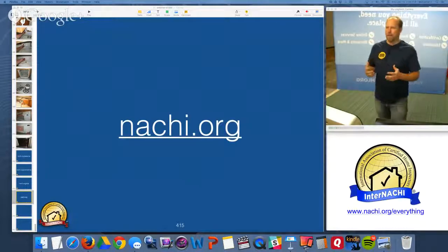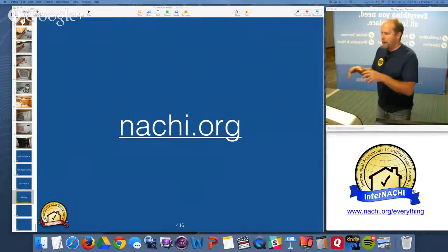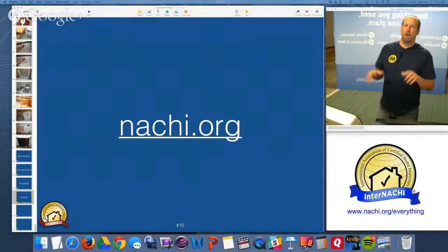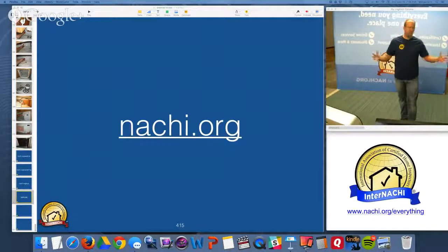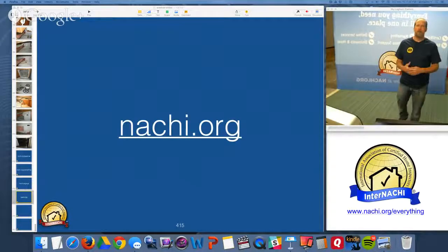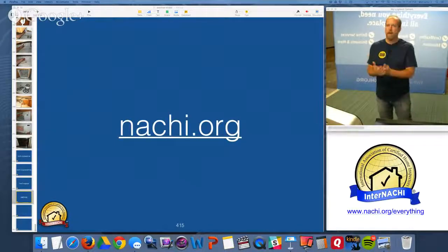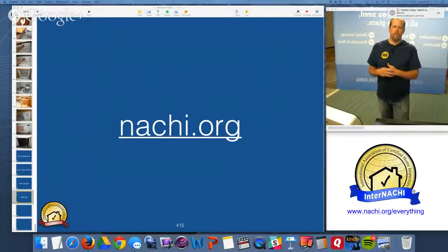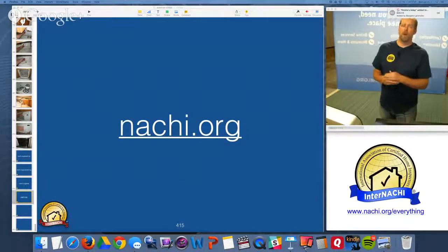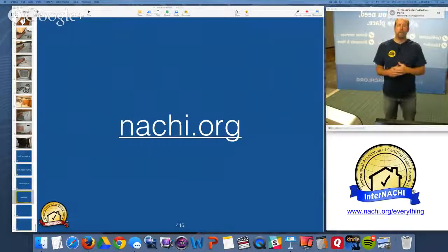So S-traps is like one of the easy things that new inspectors see and point out and call it a defect. Well, you know, when you get to be a veteran, S-traps are important, but we tend to focus on really important things, like somebody could get hurt if this isn't taken care of, or some of the nuances that new inspectors don't get. The veteran home inspectors can put things in perspective, and you can absolutely see an S-trap, point it out, but it's probably not the most important thing. Trying to find something that could hurt someone is probably on my mind more than that.